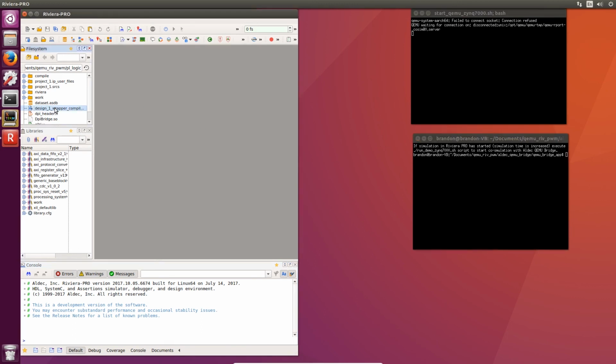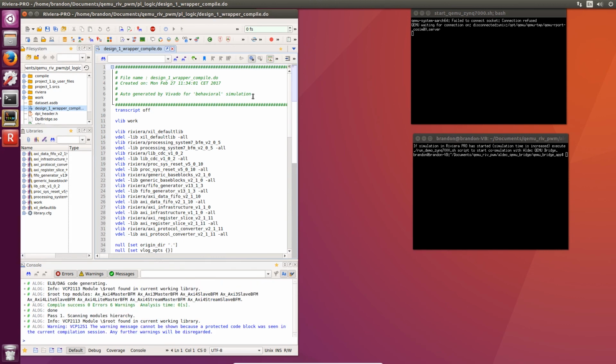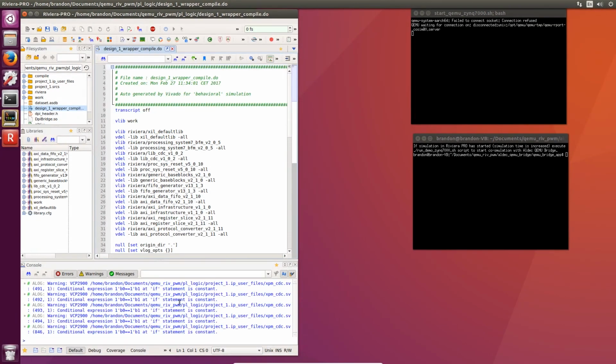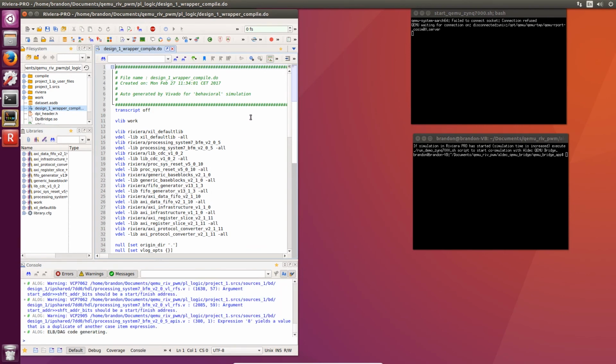With our PWM project now open and our tools primed for co-simulation, we can now run our macro within Riviera-PRO to initiate the simulation. This script will go ahead and run the design, and once completed, simulation will begin. We can verify this by observing the simulation timer starting.